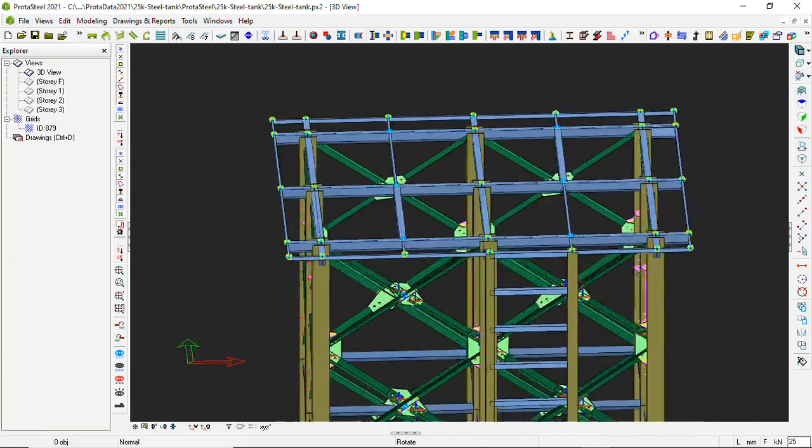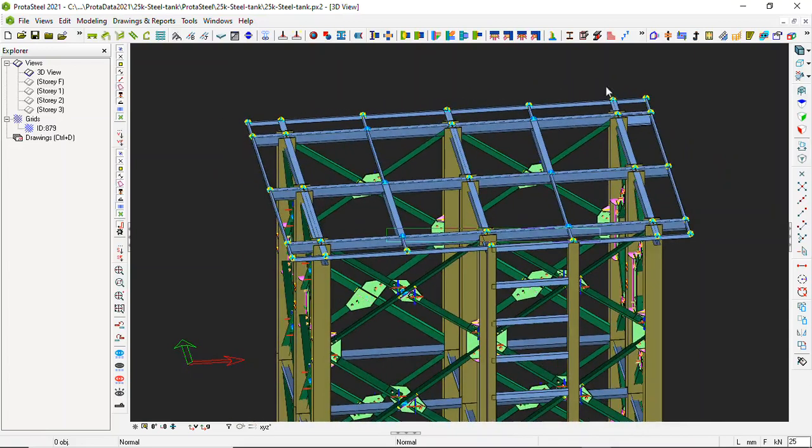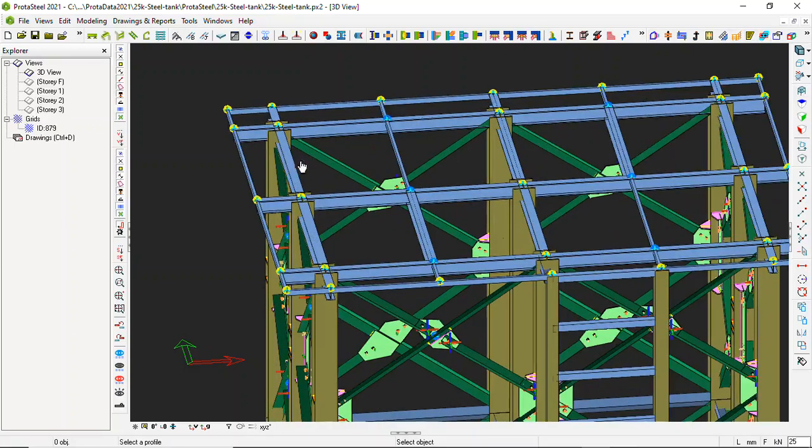Yes, we can have something like this. Now we can insert plates around here. We pick a steel plate and select the 4 edges that are covered by that steel. If I click, you can see now it's a plate, no more a concrete member.